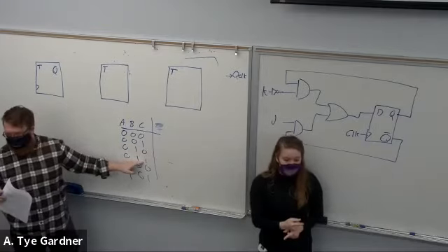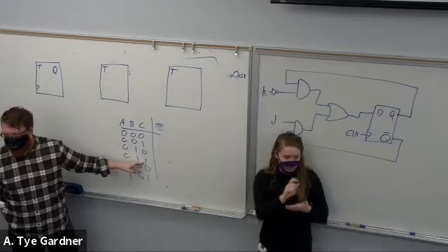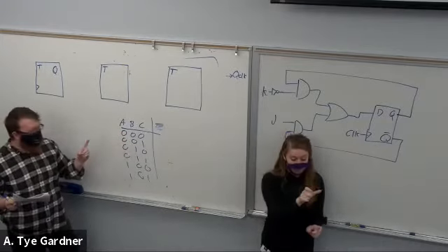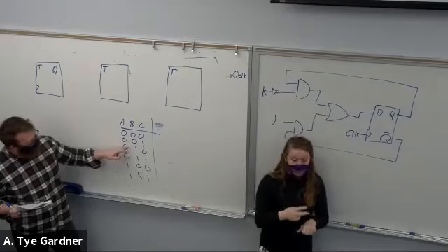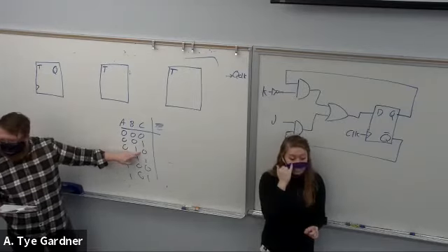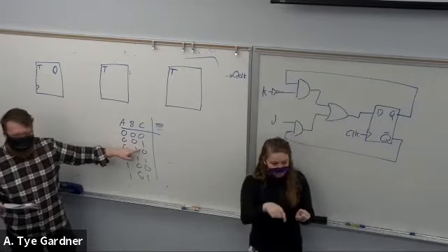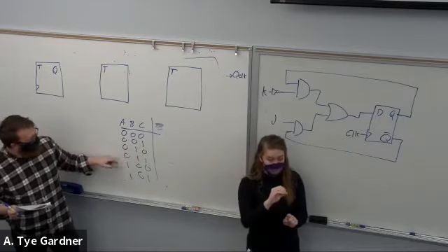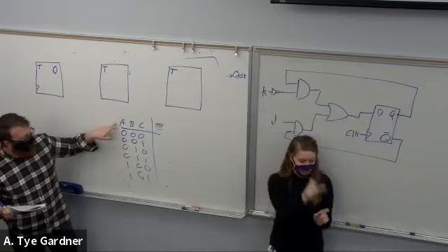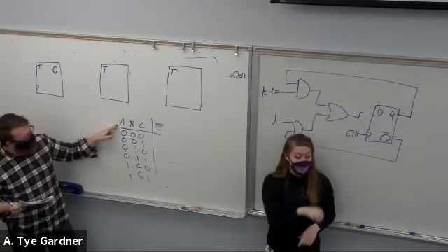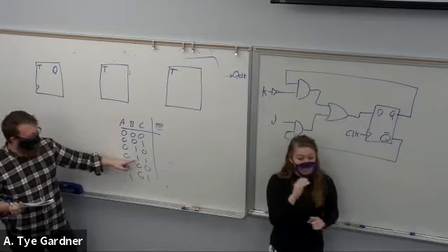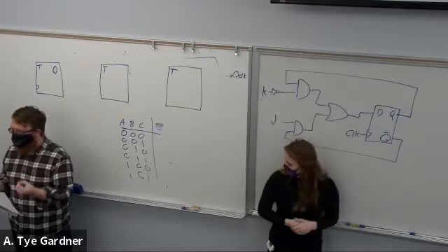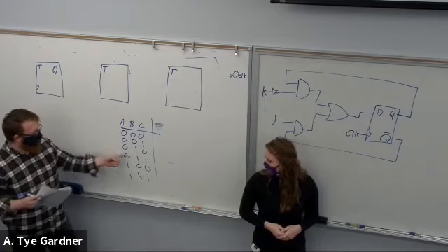And I use this trick to help me draw out binary so I don't have to like count in binary. The second column toggles every 2 times. Or you notice it toggles when I have a falling edge, when I go from 1 to 0 in the previous column. That same thing holds true in the third column. So A to B, A toggles when B goes from 1 to 0. Right? So there's this consistent moment when we change.